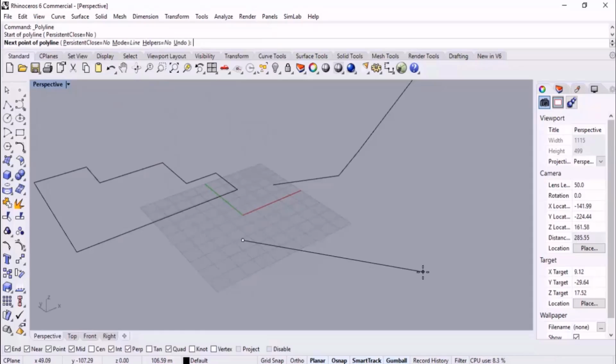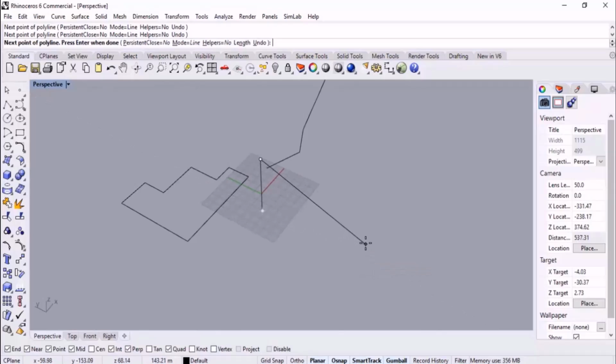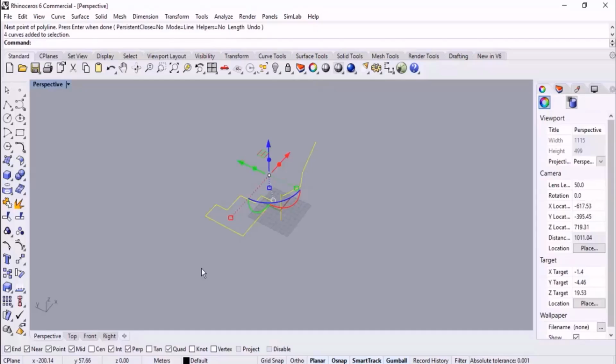Here if I specify a point in the scene, then secondly I'm going to specify the point overlapping the previous one. I hold down Control and then I click. What would happen? Or if I move the mouse, what shall happen? Let me tell that again. I have a specified point. Then for specifying the second point, I move the marker overlapping the previous point. I hold down Control and then I click. If I move the mouse, what shall happen? Yes, we will have a perpendicular line to the plane, as you can see, which is very practical. So don't forget to practice this lesson.